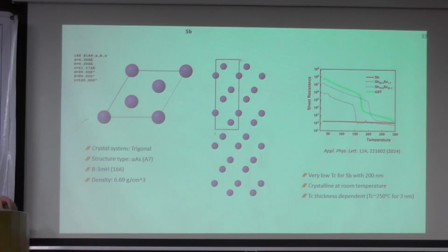If you reduce the thickness of this film, you can stabilize the amorphous structure of these materials. You have to reduce it to 5, 3 or 4 nanometers. Then you can stabilize this phase for a while, but then it spontaneously crystallizes again to the crystalline structure. So how to deal with this problem?